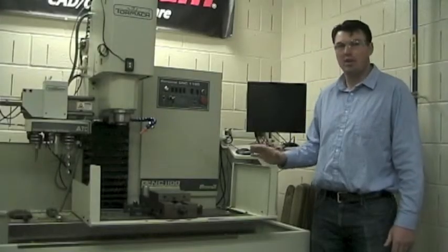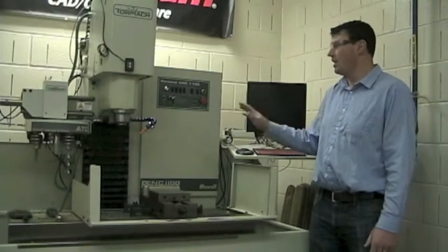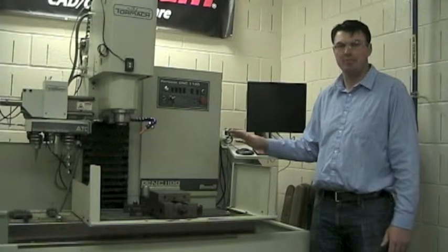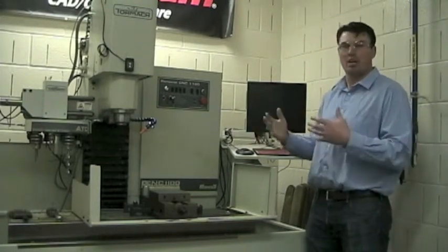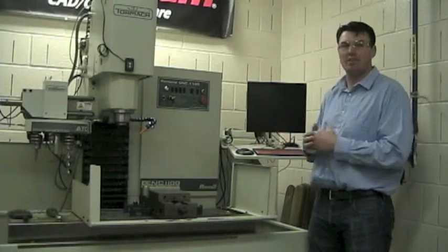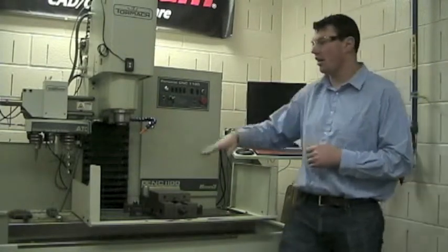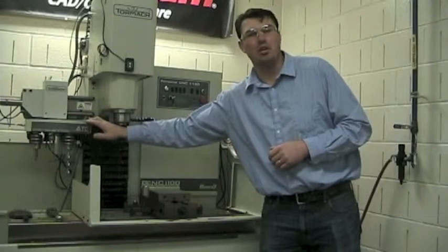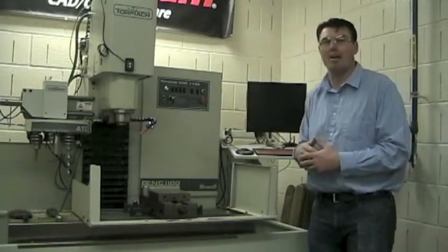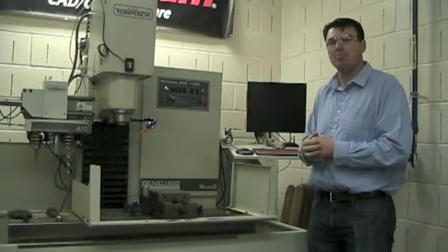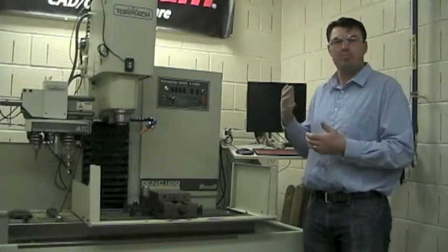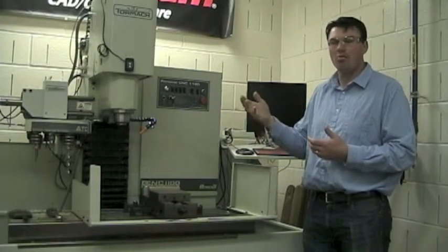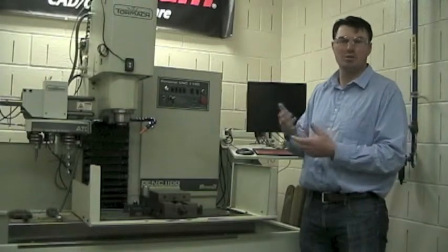Welcome. In this video we're going to cover tool setting on our Tormach milling center. Now tool setting is a process in which we're telling the machine the length of the different tools that are in our automatic tool changer, which is very important because as our machine programs run and tool changes happen, the machine needs to know that there is a difference in height between the various tools.